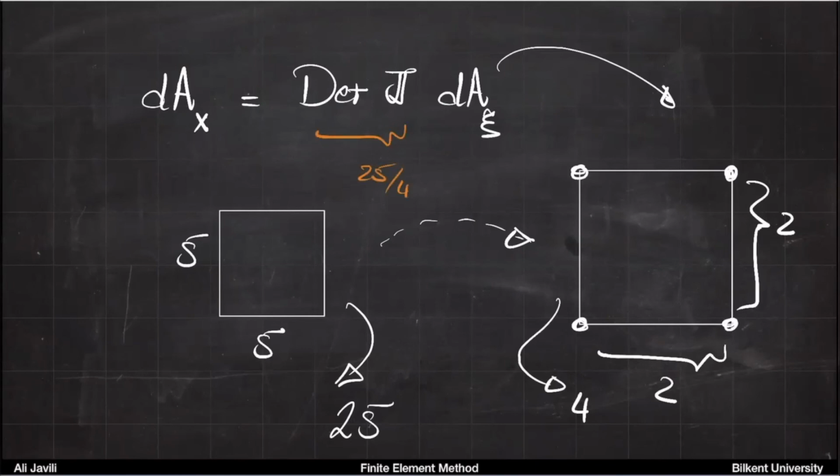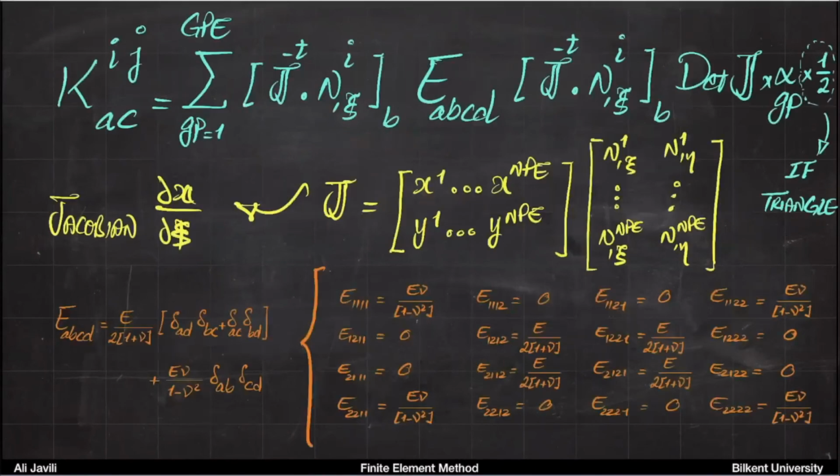All right. So that was everything for today. The most important thing for you is really to just look at or use this slide. That's all you need for your computational implementation. Now we have answered all the questions. One last thing, once you write that function in terms of C and you do the integration, remember there is that weight factor for the Gauss integration. And if you have a triangular element, there is a factor 1/2 in that formula. So don't forget that 1/2 if you have a triangle element.